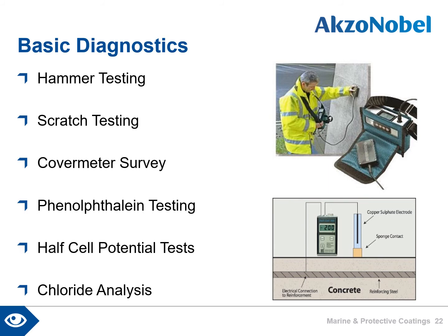Looking to the top right hand of the slide, we can see a cover meter survey being undertaken. This will establish the depth of concrete cover by checking at representative reference points. Once a reliable data set has been established, the rate of carbonation can be estimated and a preventative maintenance strategy agreed. Low cover in new construction can be quickly rectified with the application of an advanced polymer-modified cementitious coating, a 2 mm layer being equal to 100 mm of normal concrete cover.